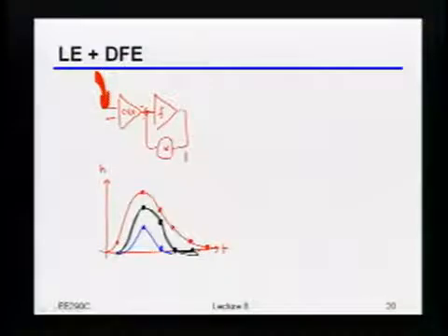More questions? Yeah. So basically, here you could make the first pole of the equalizer half of what you would otherwise. That's right. Roughly speaking, yes. Now, it's not exactly a factor of 2 because it depends on exactly the channel and things like that, but ballpark, that is about what it ends up being. And you can imagine if you cancel even more of these things, you may even be able to back off further, although for most channels there are diminishing returns after that point. But indeed, there is about that factor of 2 that it buys you in terms of the bandwidth of that linear equalizer.